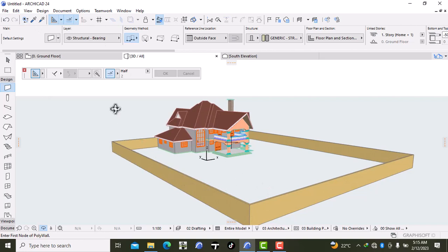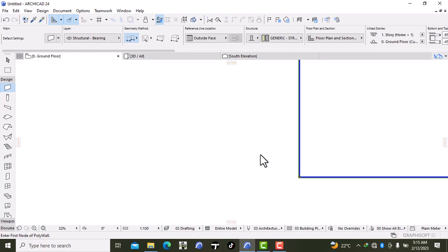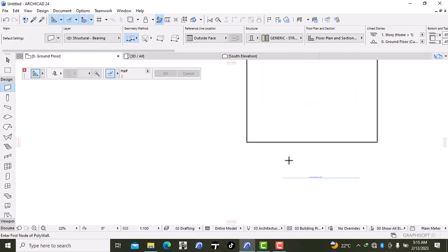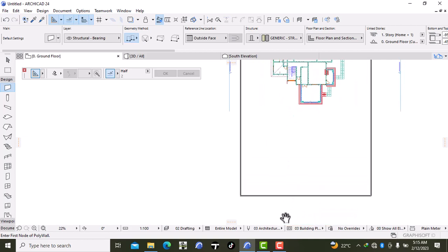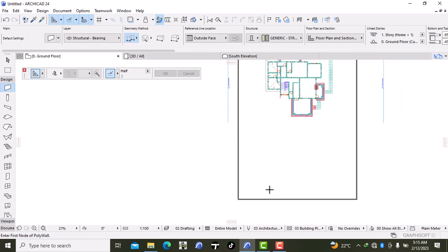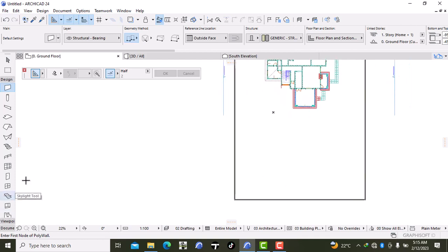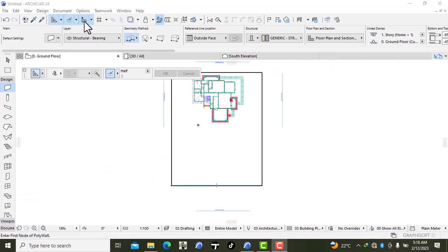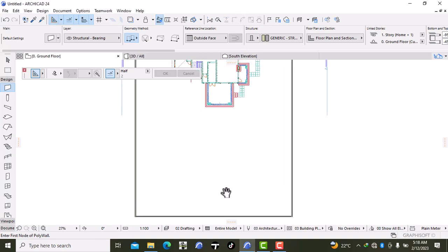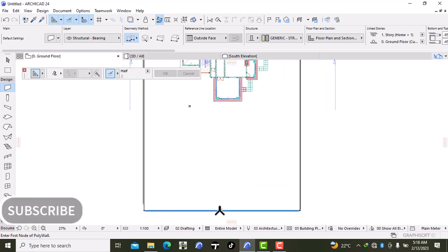I can go ahead and just highlight where I'm going to have my gate. So I can have my gate coming at a point like this very edge over here. I want to place my gate somewhere here in the middle.